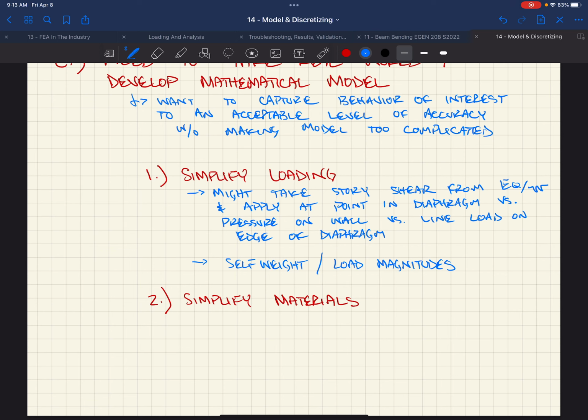We're not going through and applying the earthquake load. That load's based on mass, mass and acceleration. We're not doing that at every little member. Some of the advanced analysis methods like time history, if you guys were talking, in Mike's class, modal analysis, time history analysis. You jump to another level where you have more weight, I guess no pun intended, weight associated with the weight of our members in your analysis. They play a bigger role when you're looking at time history and you're actually shaking a structure with a real earthquake. So we can ignore self-weight sometimes.